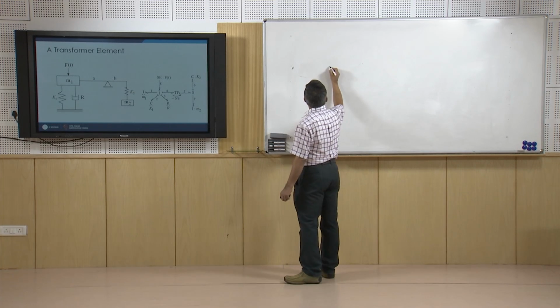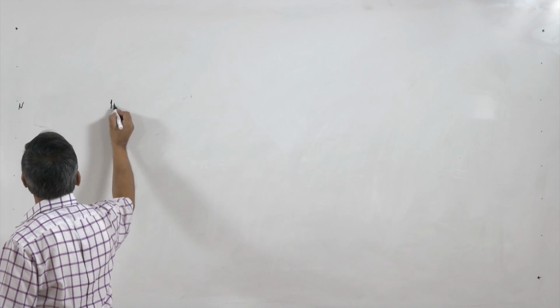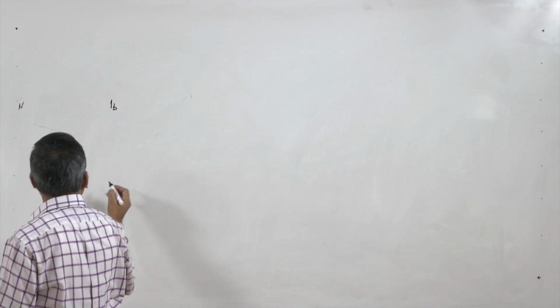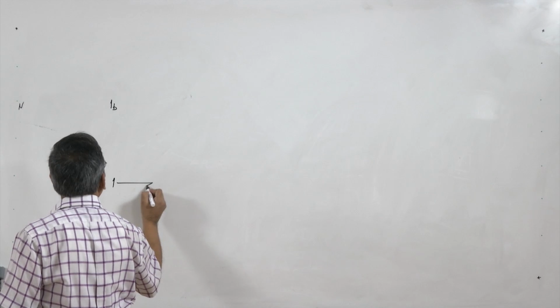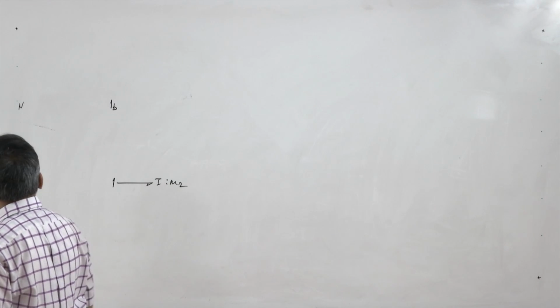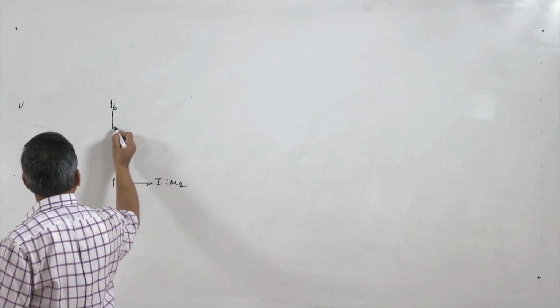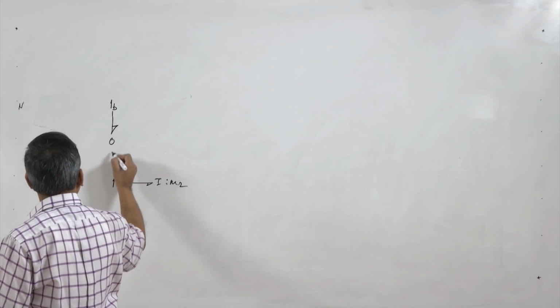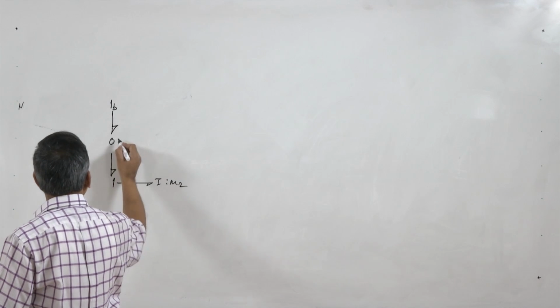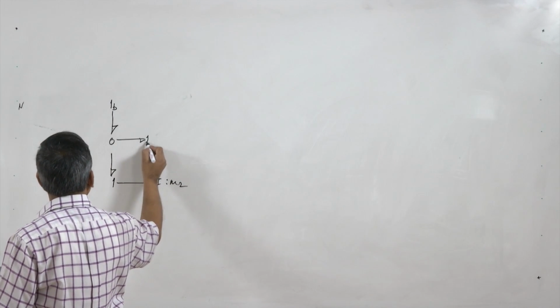We can find out the velocity here at the end of the say lever B, okay, and I have the velocity of this I is equal to m2, and I can take the velocity difference basically here in a 0 junction like this, and whatever difference comes here I can attach a spring.